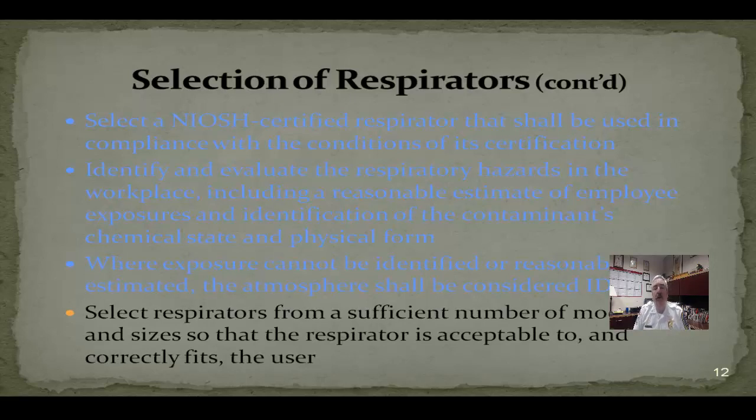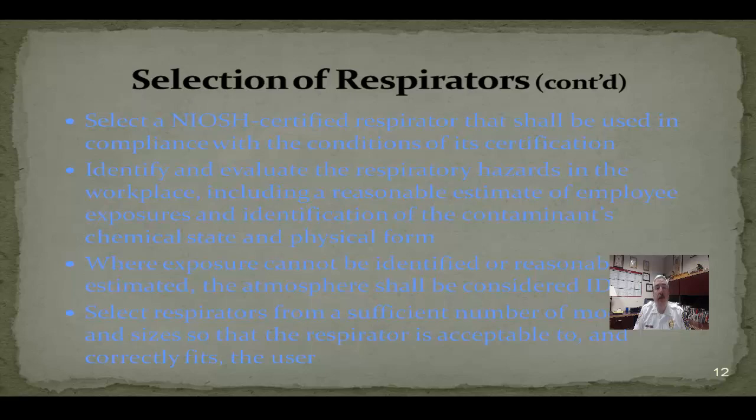Select the respirators on the specific types, models, and sizes that are provided for you. Not one size fits all for the higher end respirators that we have. So even with an N95, they're small and large. With our full face SCBA face pieces with the adapters and cartridges on them, those again are size small, medium, large. So make sure that you've got the right equipment for the environments that you're going to go into.